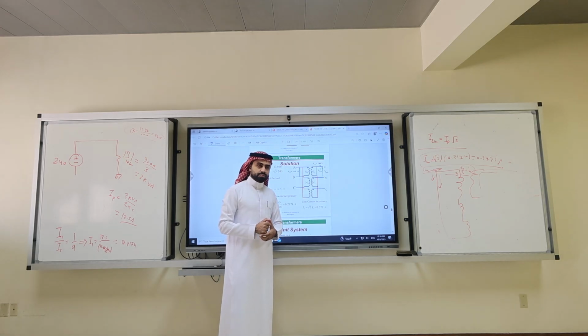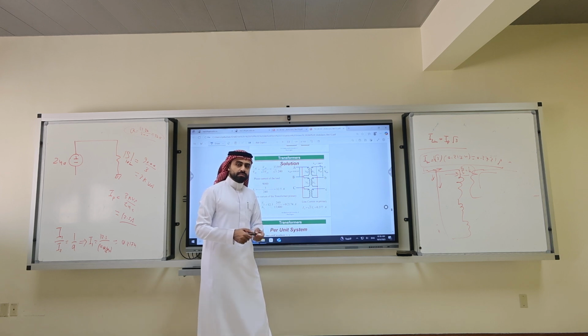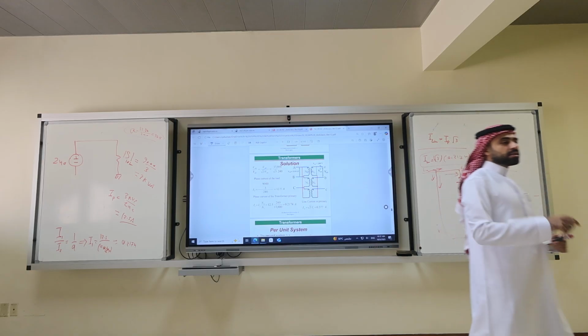An equal branching. You mean why didn't we just multiply by 2? No, why? How would you know its value? Because the phases shift. You have a phase shift in the angles. When you have phase shifts, they are the ones that create the square root of 3. Do you remember? Use your calculator: 1 angle 0 minus 1 angle 120.